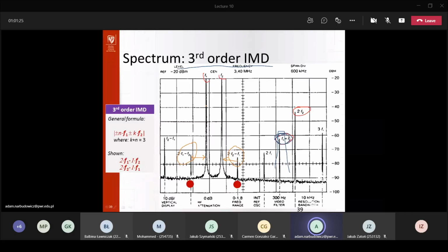However, because the bandwidth, as I mentioned, is quite heavily used, it was challenging to have a single block of bandwidth from the beginning, right? So some of the frequencies are scattered across the spectrum. That means that LTE is using quite a lot of different frequency bands, quite a lot of different carrier frequencies, which again means it is very prone to intermodulation, simply because of the more frequencies.